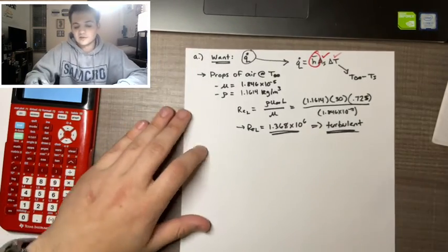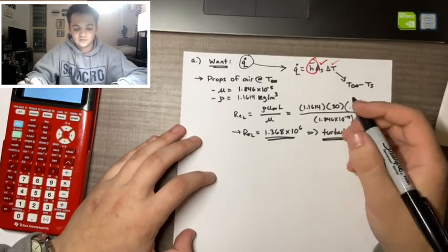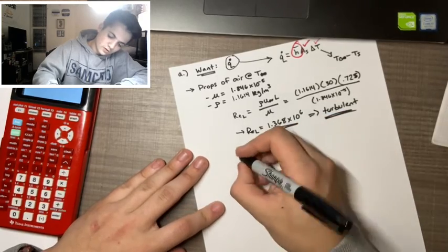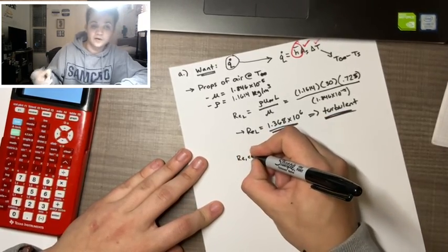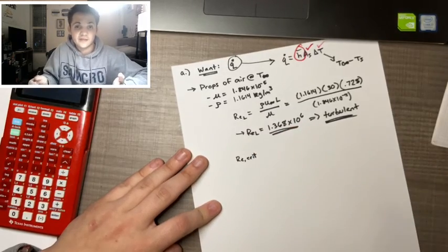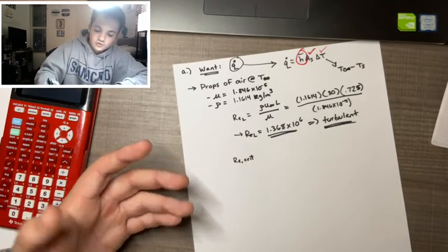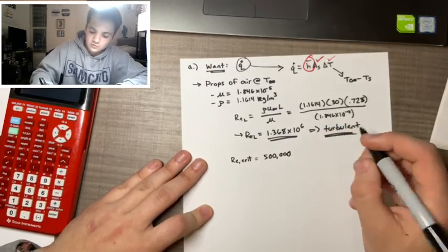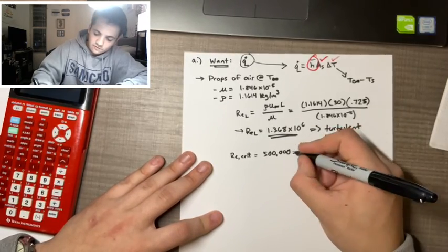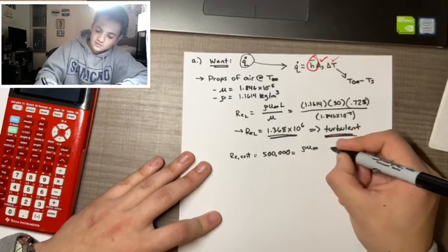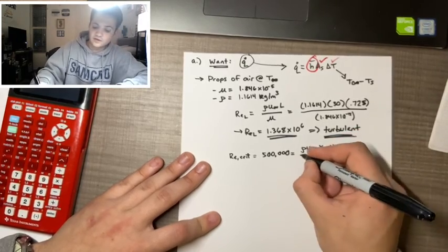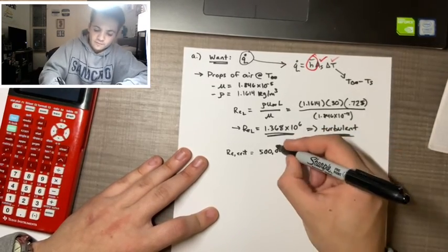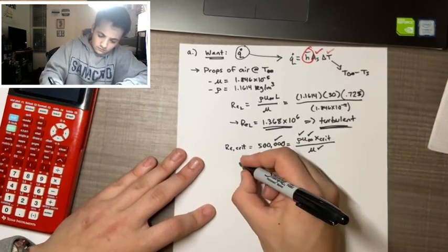So how do we check that? Well, we know there's some critical distance x down the plate where the flow is going to turn from laminar to mixed or turbulent. So the critical Reynolds number, which is the Reynolds number at that distance x, is going to be equal to 500,000. We set that equal to the Reynolds number equation, rho u infinity times x critical over mu. We have rho, u infinity, mu, and 500,000, so we can get our x crit from there.